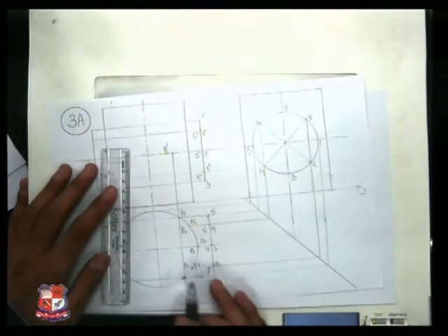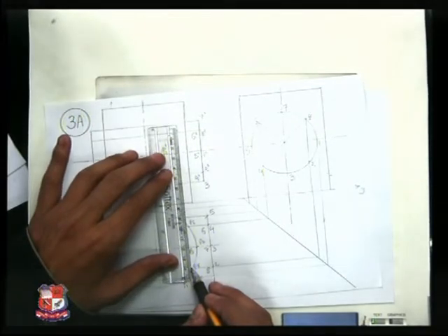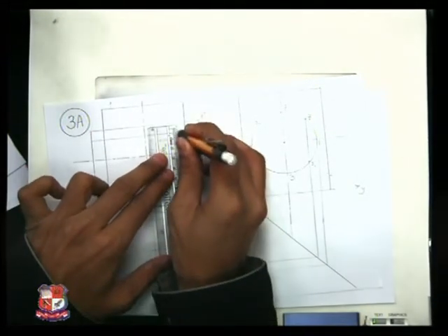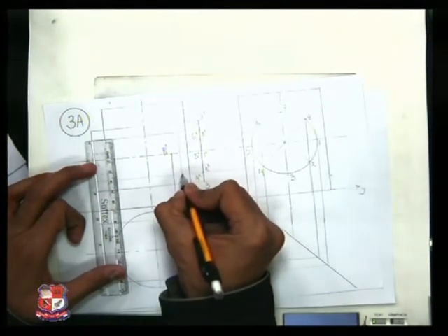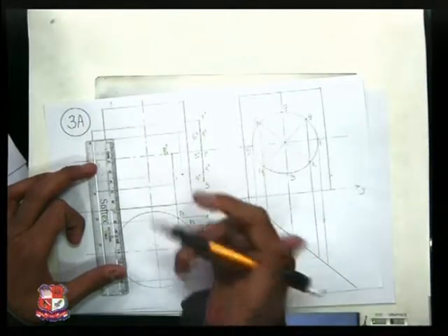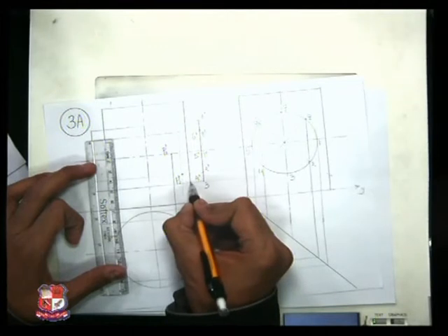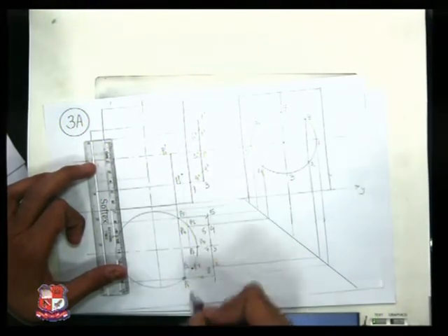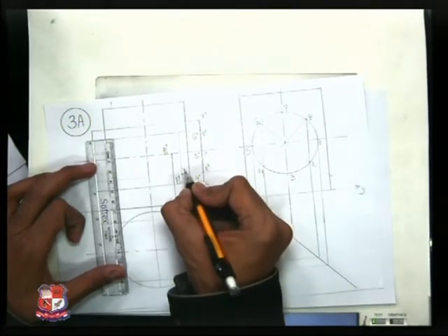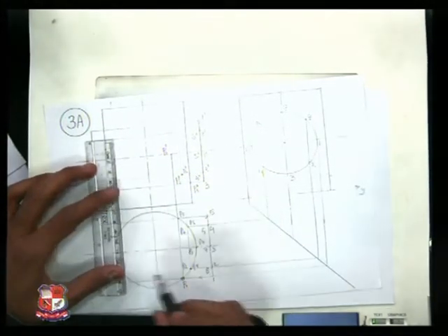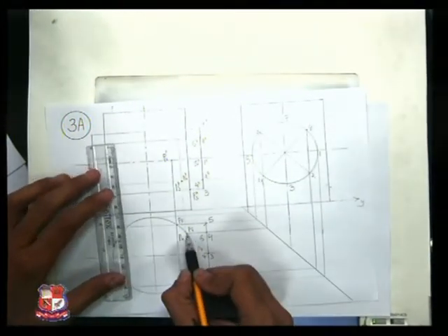Now to locate the position of point number P2, from point 2, here is point number 2. From point 2, draw a straight vertical line like this, and that will cut the horizontal line from point 2 at one point. This is point number P2 dash. And from point 3, a horizontal line from point 3, and here a vertical line from point P3. This is P3 dash. Similarly, P4 would be here. For point number 5, from 5 draw a horizontal line, and from P5 draw a vertical